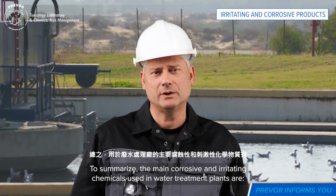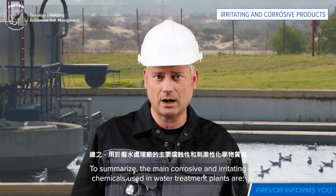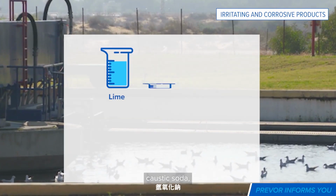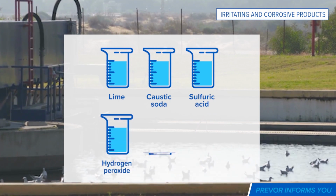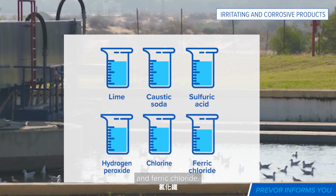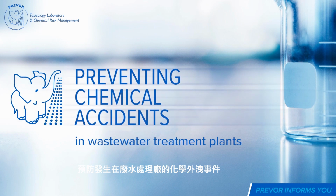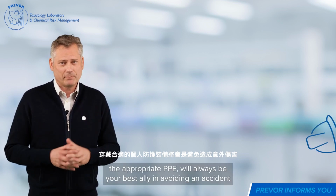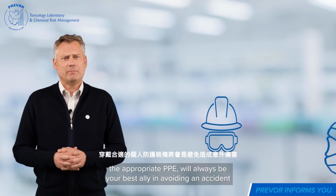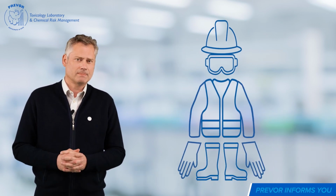To summarize, the main corrosive and irritating chemicals used in water treatment plants are lime, caustic soda, sulfuric acid, hydrogen peroxide, chlorine and ferric chloride. Training your staff on these risks, combined with the wearing of the appropriate PPE, will always be your best ally in avoiding an accident involving a chemical splash.